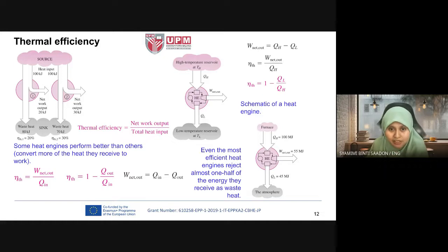We reuse this waste heat. Or another method is, for example, we add a regenerator to the basic cycle. So this regenerator will use the higher temperature of the heat in the cycle to reheat the working fluid inside the boiler or the combustion chamber.